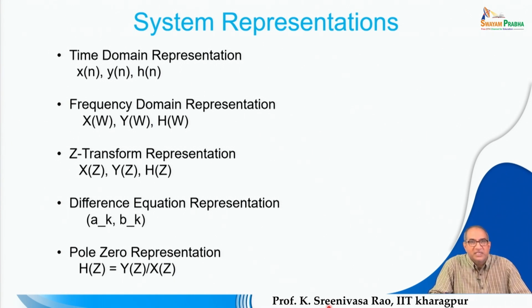For every shift we will see the overlap between the 2 sequences, and that will be estimated as the convolution at different shifts. Whereas in case of correlation, out of the 2 sequences, one sequence is maintained as static, whereas the other sequence is shifted without flipping in the positive or negative direction, and for every shift we see the overlap area between these 2 sequences, that happens to be the correlation for different shifts between the 2 sequences.